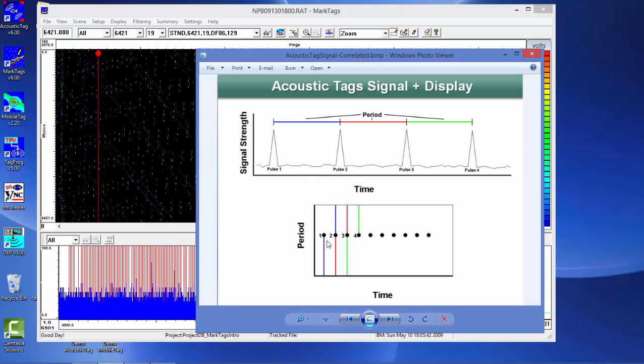And so since we know precisely when the next transmission will be, when we display the data, we set the vertical scale of the main display to view precisely that transmission time. And if it's set for the correct period for that tag, then all the signals for that tag will be lined up horizontally, since it is set for the proper period scale.